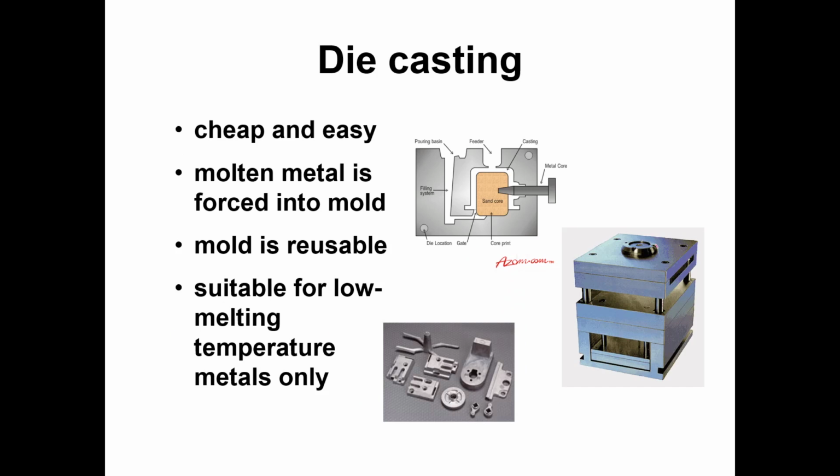All right, then that brings us to die casting. Now, if you want to make millions of mass-produced parts, you need an automated machine to do that. So a die is a mold that can be automated. There's pieces that move robotically or whatever, and you inject the molten material, and then the mold comes apart automatically, and you can just repeat that process over and over again.